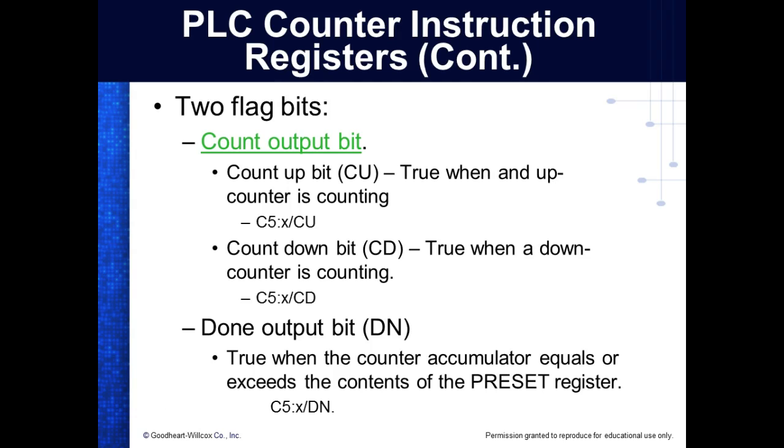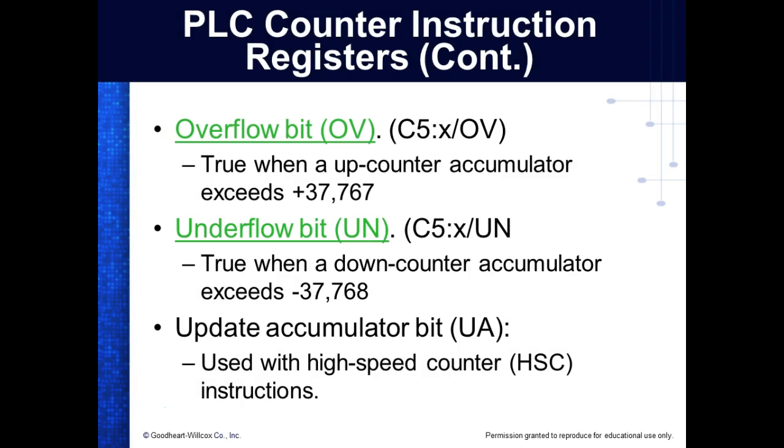And this is where it really gets weird with down counters. The problem is that we're dealing with binary numbers, and we've got to be able to count down or count up, which means we have to represent negative numbers. It's a 16-bit number. I'm not going to teach you how, but I use a method called 2's complement to represent signed numbers. You sacrifice the most significant bit to indicate the sign. If it's a 1, the number is negative. If it's a 0, the number is positive.